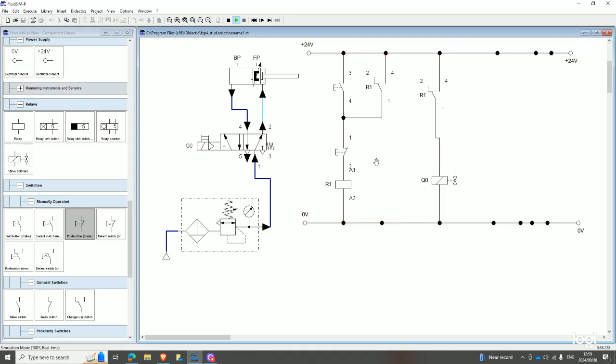So now I can just press this. As you can see, it opened up for the instant that I pressed it, and as soon as I let go of it, it closed back up again. So it's used to just cut the current in a circuit. You can observe: I press this, current passes through it up until a point where I need to cut the current, and that's when it retracts. So this is my first push button, this is my PB1, this is my PB2, and that's how you latch an electrical circuit.